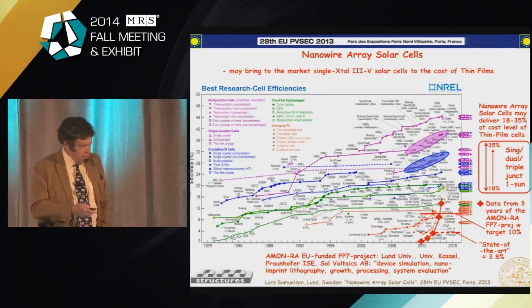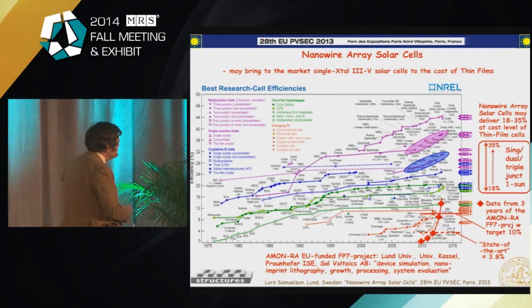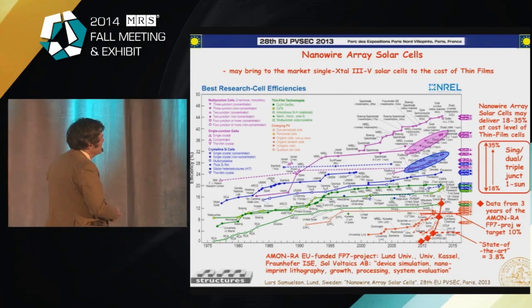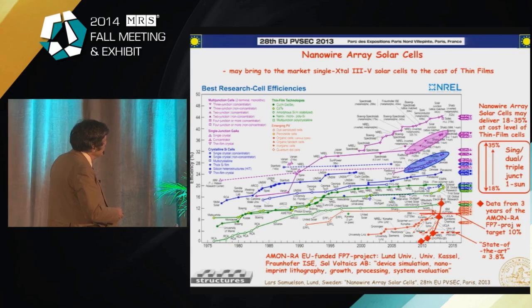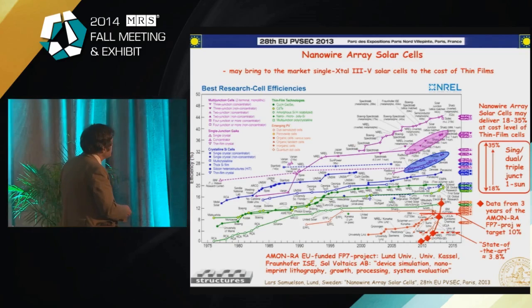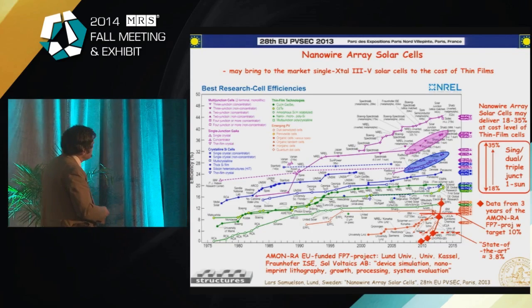Single crystalline silicon, for the market, is typically in the range of 18, 19%. You have some master technologies that bring silicon beyond 20, maybe 21, 22% or so, which is, of course, a fantastic achievement. And then you have the gallium arsenide, planar structure still, where you can get up to more than 30% in efficiency. And if you do dual junction or multiple junction solar cells, still with a single sun power without concentration, that has been demonstrated to go up to the high 30s.